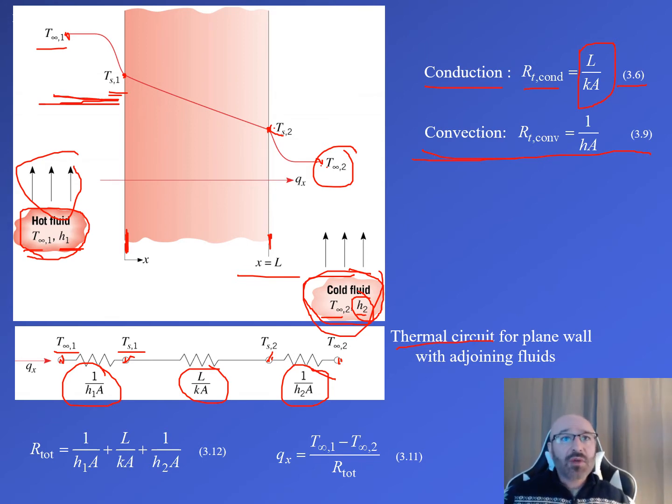What's going on from here to here? Especially as we get into some composite structures where there's more things going on than just one solid material in the wall. We have different H values. We have different things that we need to plug in there, different K values if we're dealing with the actual conduction value as well. Is there an air pocket in the wall? Are we talking about a double insulated window? All those types of things.